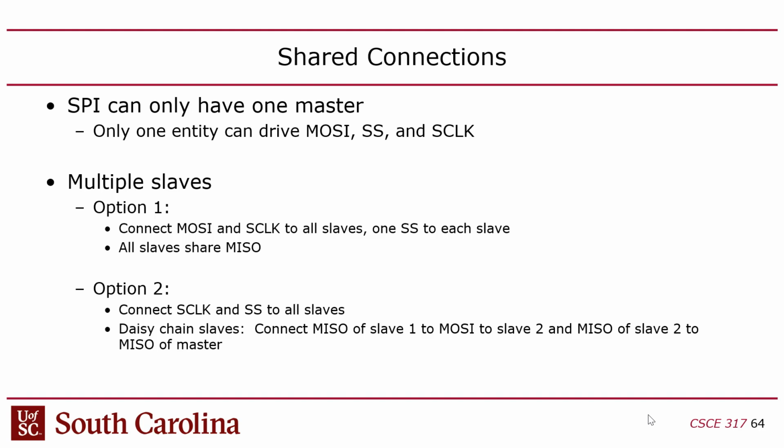Maybe the data sheet will say you can only do that up to 6 or something, but it would be application dependent, right? But the idea in the protocol is that as long as you hold that SS line low, it'll continue to do the read or write.